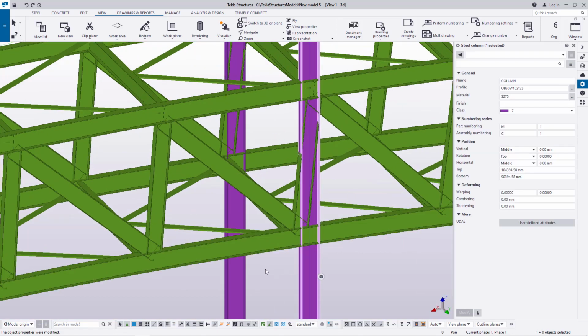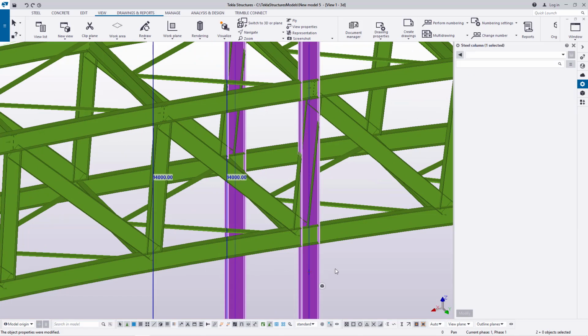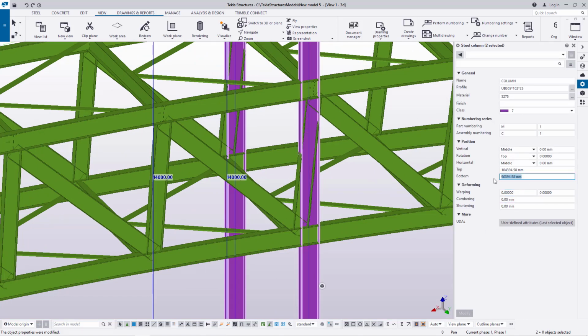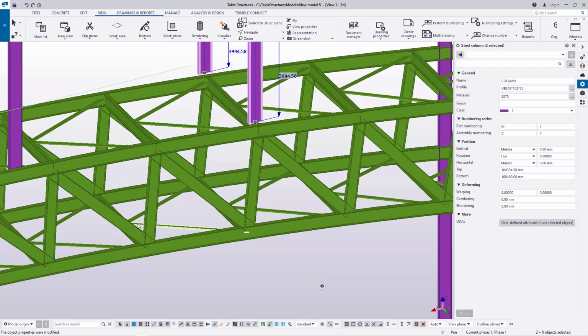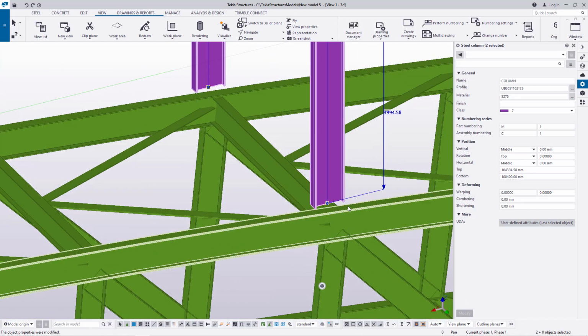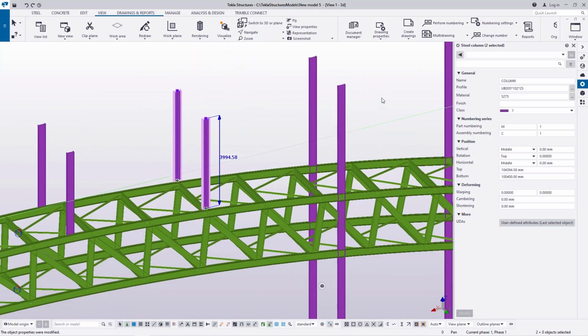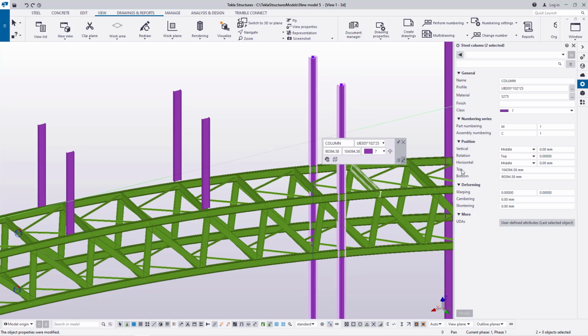Select on that, select on this, press Ctrl and double click on that, select on that and double click on this, and come to bottom under position here. And how much do you feed here? We'll just feed 100,400. I think that will work much better. But it has gone off the mark, but it's still okay. And I'll come here again and select on that, double click on this, and come to position under bottom here, and what I'm going to feed here should be 99,700 approximately.